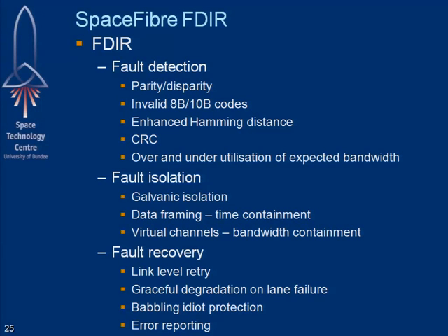So we're using acknowledgements, negative acknowledgements, and what we call polarity of the acknowledgements to remove the need for a timeout mechanism. So this means if you extend the length of the wire, then we automatically adapt to that.